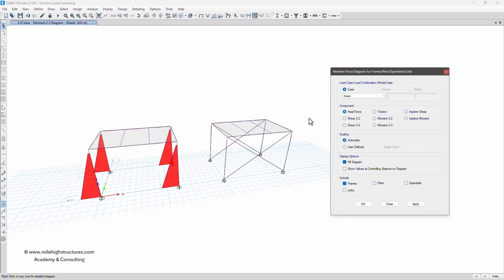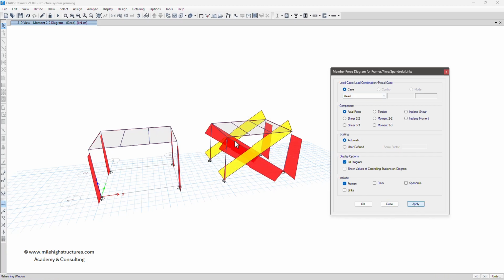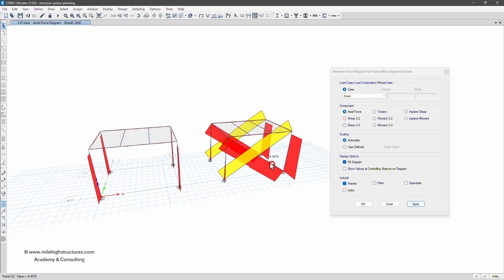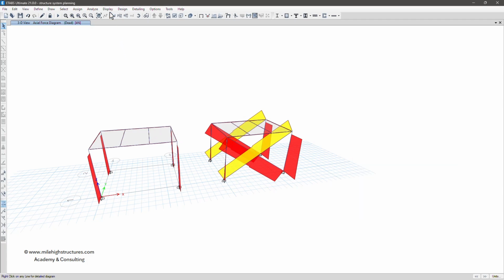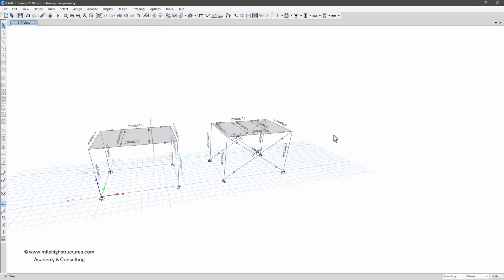Whatever lateral forces are coming have been converted into axial forces here. So here you can see that 6.4 kN is the axial force, and 6.05 is approximately what we can say is a tension force here. So this is in compression and this is in tension. That is the main criteria, the main system of why and how the bracing is provided. Now that is one concept.